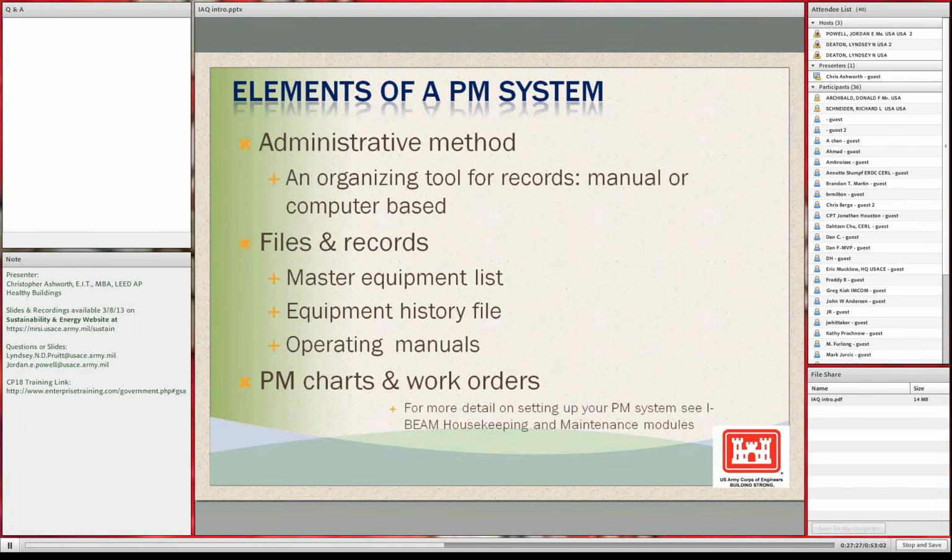And keeping these files and records and having the master equipment list are huge, not just for, let's say, eventually going through a retro-commissioning program and maintaining the energy of the building and maintaining the systems and the life cycle of the systems, but also about the indoor air quality of the systems, knowing where you may have dead legs in your water system, knowing where you have your shut-off valves, and if you have the proper shut-off valves in the building, etc., so we don't have backflow of cooling tower water into your system, for example. Having these records and documentation that are accurate is hugely important to maintaining and managing the indoor air quality.